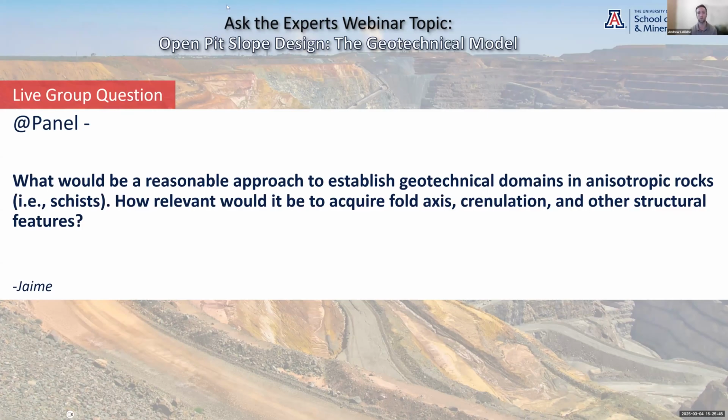Yeah, thanks, Jillian. I think it's super relevant to the presentation that I had given. This speaks right to getting back to, once you've established your domains, what are those domains going to perform like in the pit that you're designing? In the case of anisotropic rocks, the performance and the instability considerations are in the footwall. When that anisotropic fabric is dipping out of your slope versus dipping into your slope is markedly different. And so you have to have your mind to that as a starting point.